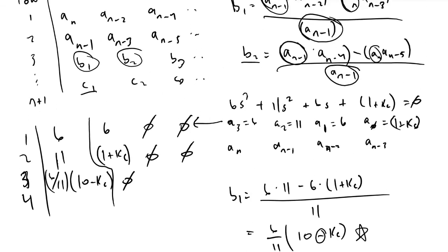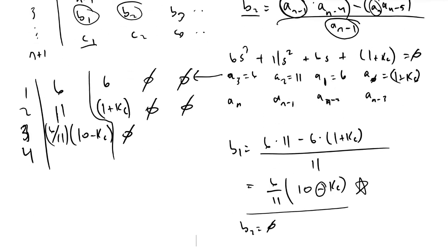And A naught, as we'll recall in this case, was simply 1 plus kc. And so we don't really need to rigorously evaluate, but it's just a nice little thing to know. And if you rigorously evaluate it, you will find that you get your necessary condition. And so it is another sanity check you perform along the way to see if you made any algebra mistakes.